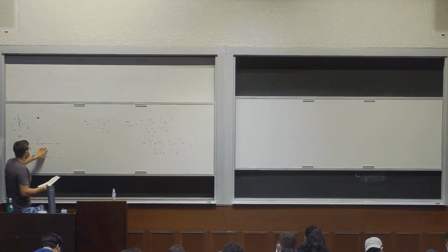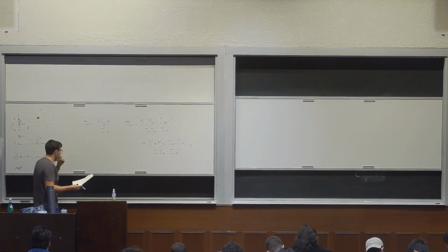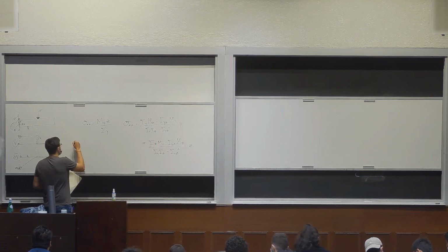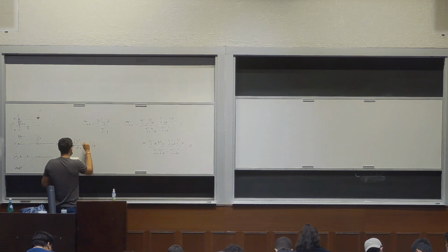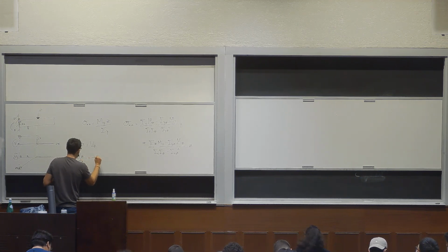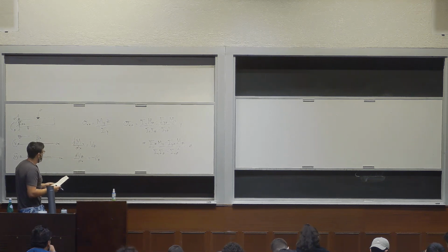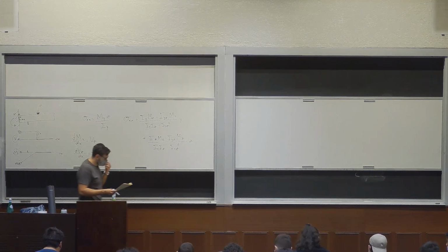Another important equation for these too, the relationship between the shear and the moment. It's not too important for this chapter, but just to have it in case you're given a problem where you first have to solve the shear moment diagrams, is, like I said, dM/dx equals Vz, in this case dMy, and dVz/dx equals negative pz. Okay. And so yeah, this is the brief overview of what we talked about last time.